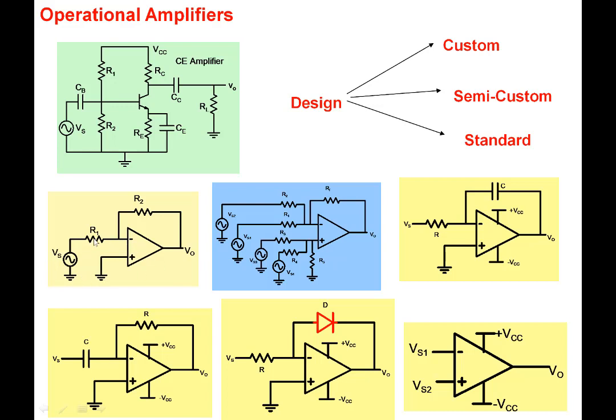All you need to do is add a resistor R1 and an R2, and the ratio gives you the gain. So apart from the fact that you have an op-amp and you can do very interesting things, what it conveys is a very important principle, a very important principle of semi-custom design. You do a design which is very complex, but with very simple interfaces, allowing a non-specialist to add something to it and customize it to his or her requirements. So the op-amp, in a very beautiful way, illustrates that.